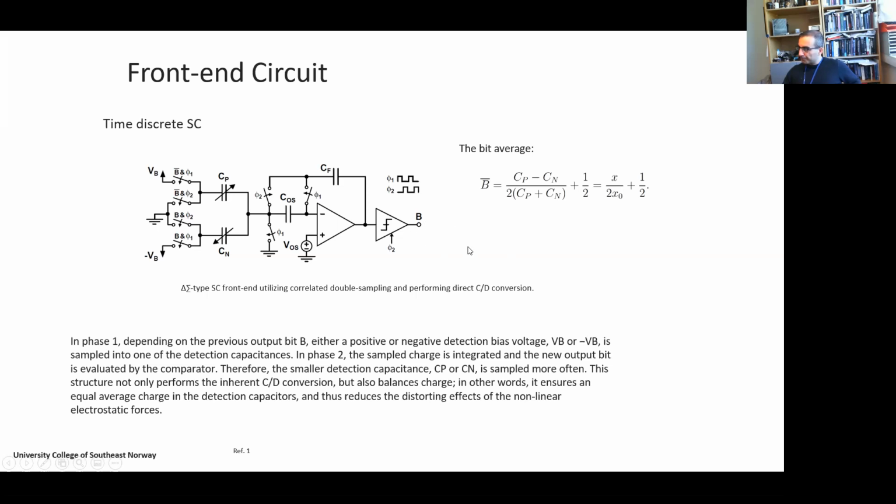kind of digital signal. So this one is based on the delta sigma modulator technique, signal processing. Delta sigma modulators are a kind of AD converter where the output is time varying, a pulse train, and the information is stored in that.